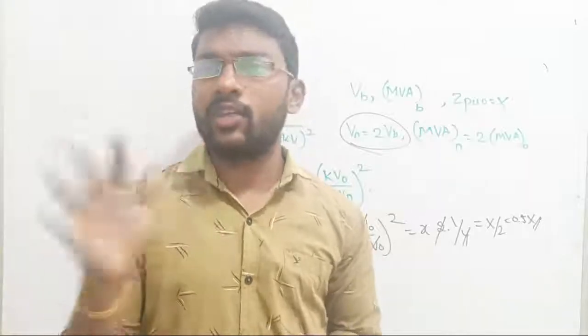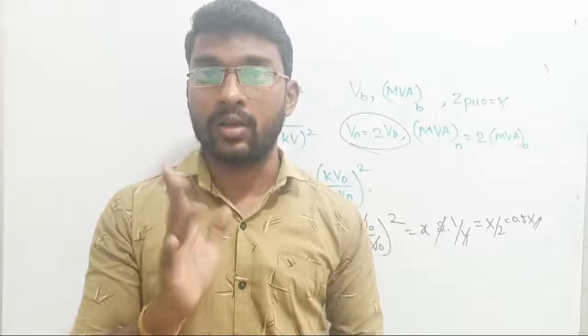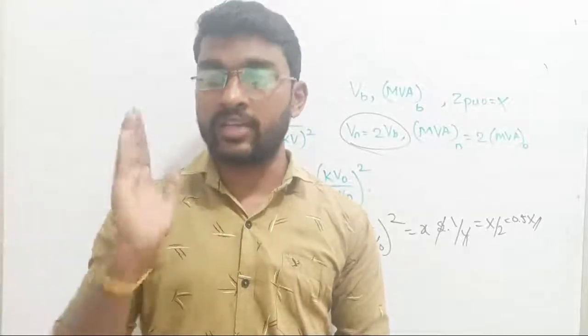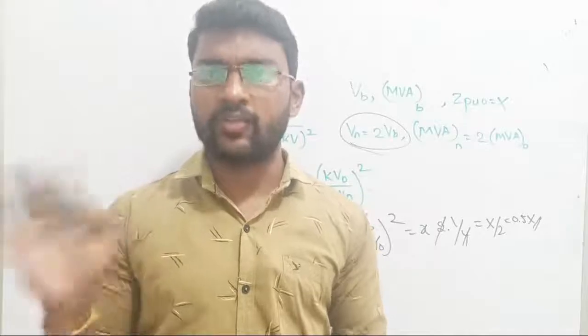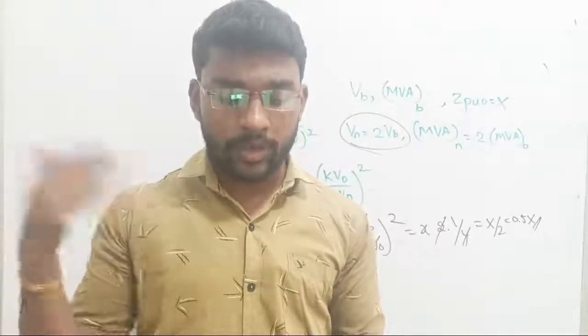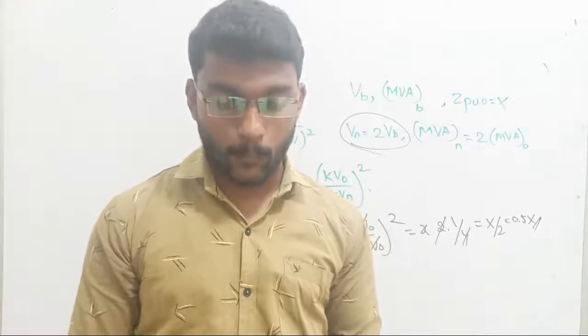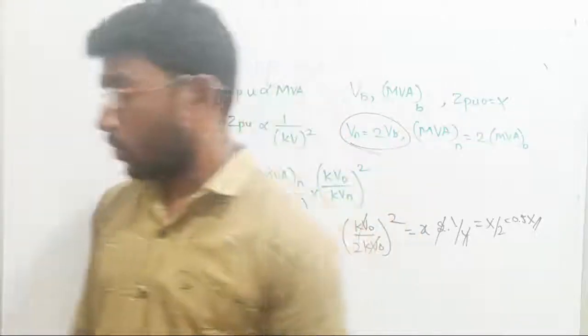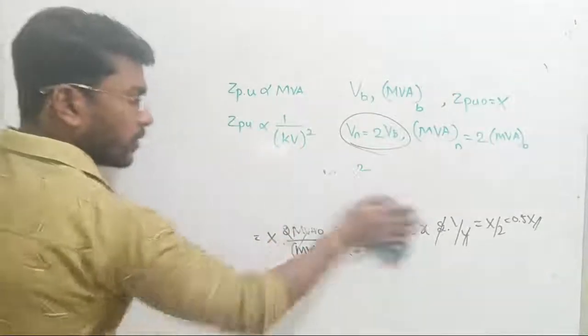Reduce பண்ணுங்க, அது ஆட்டோமேட்டிக் ஆன்சர் வரும். See, அந்த j எல்லாம் தூக்கிடுங்க. நம்ம அந்த ஃபார்முலால j எல்லாம் சொல்லிட்டோம், மேக்னிட்யூட் கன்சிடர் பண்ணும்போது j எல்லாம் தேவையில்லை. x1, x2, x0, x1 enough, right? x0, x1, x2 அது அப்படியே சப்ஸ்டிட்யூட் பண்ணுங்க. 3 times xn, fault impedance 0, அப்படியே ரெடியூஸ் பண்ணுங்க. Okay, you might be right, let me proceed.